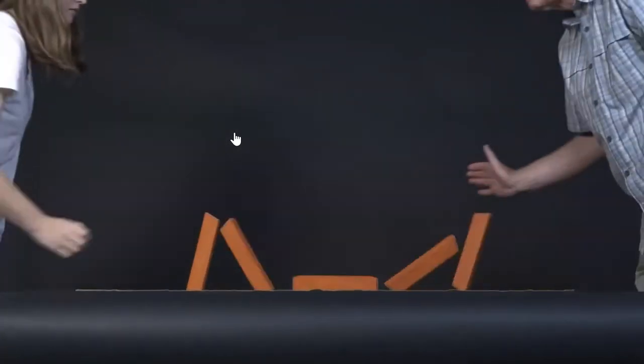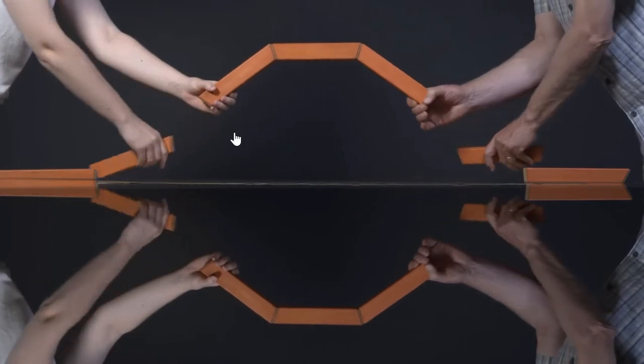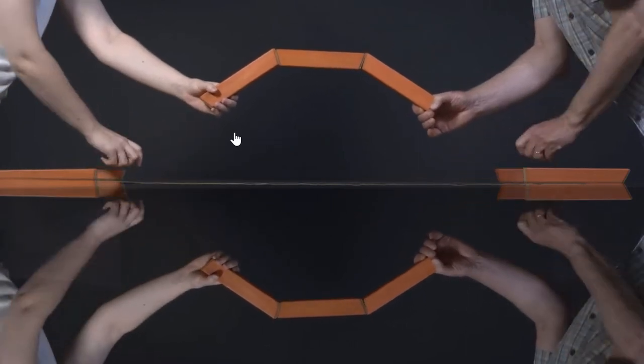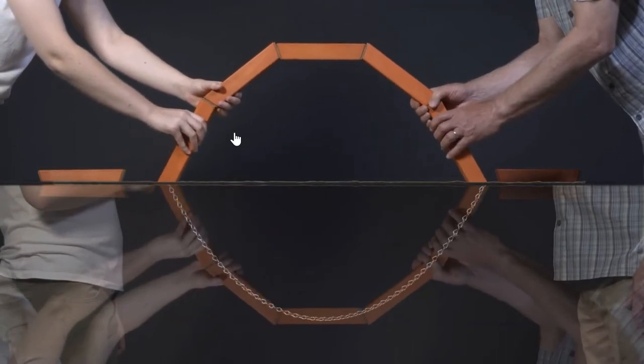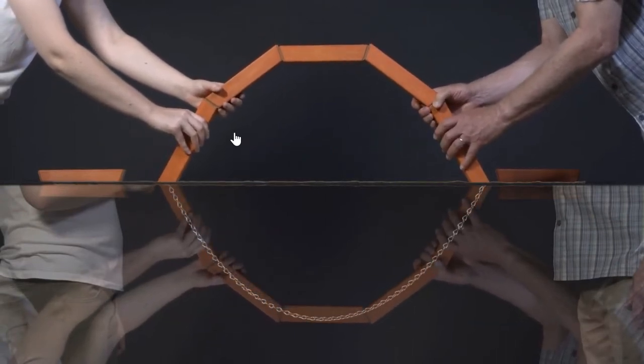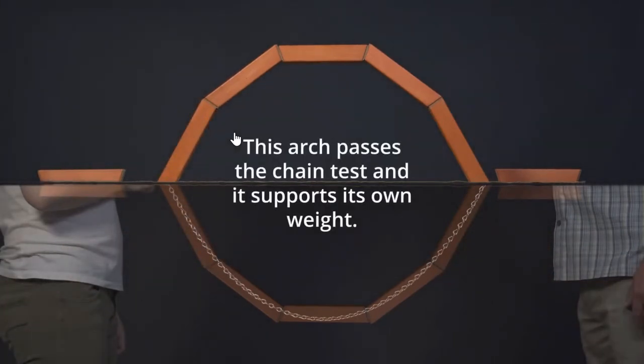One way to make the arch pass the chain test is to make it thicker. Another solution would be to change the shape of the arch so that it follows the chain shape. For this arch, we could do that by tilting the bottom pieces of the arch outwards. As you can see, when the arch shape follows the chain, it stands up just fine.